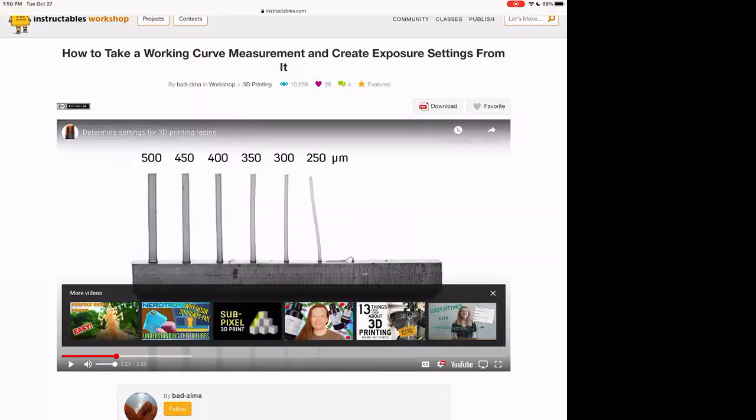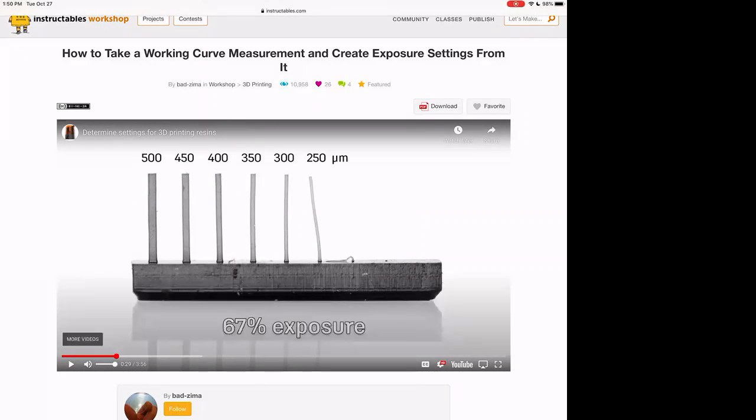I just want to pipe in here that this video also gives you an idea of feature sizes, overhangs, and unsupported material that you can do with SLA, at least in the context of the Ember. So this starts to give you a physical picture of what some of the limits are for what you can build. So just pay attention to that.